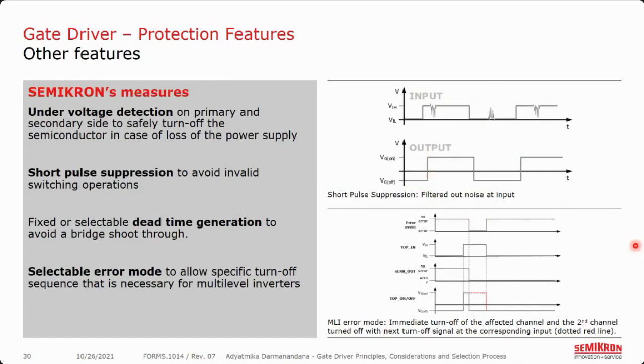Our drivers also offer different modes of dead time, where you can deactivate it or select different values. The last feature included in this presentation is the selectable error mode, which is useful in multi-level inverter (MLI) operation. In case of an error, for example a short circuit or other error signal, the affected channel will be immediately turned off, but the output of the neighboring channel will not. The driver will forward the error signal to the controller, so it has time to activate the specific turn-off sequence for the MLI application.